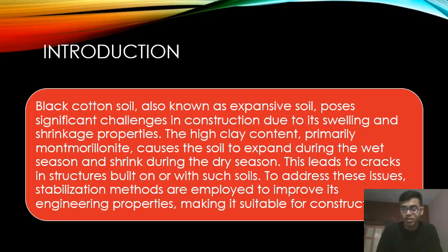It expands and poses significant challenges in construction due to its swelling and shrinkage properties, as we already mentioned. The high clay content, primarily the montmorillonite particle, causes the soil to expand during the wet season and shrink during the dry season.